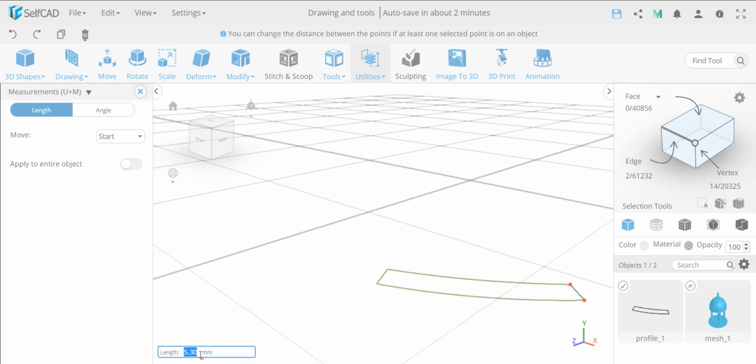So if I'm going to resize that, you see there are options: start, finish, or both. I want to equally scale them, so I'm going to type in 6 over here. This will resize this. And I can go to each of them and make sure each of them is sized the same, or I can play with this option, resize entire object. But that's basically the idea of how you can resize them.